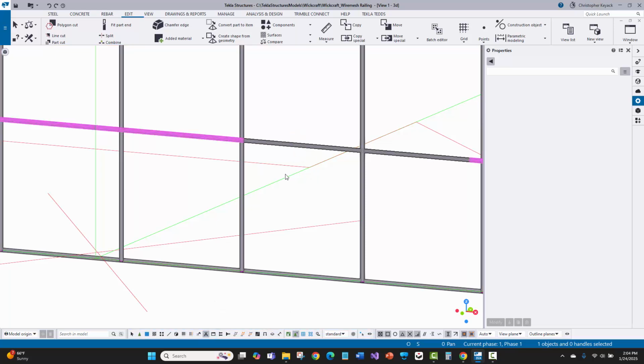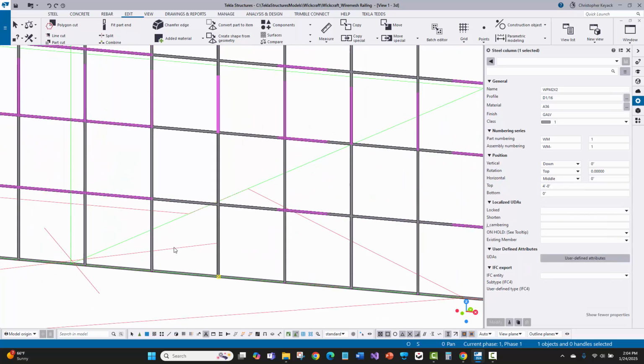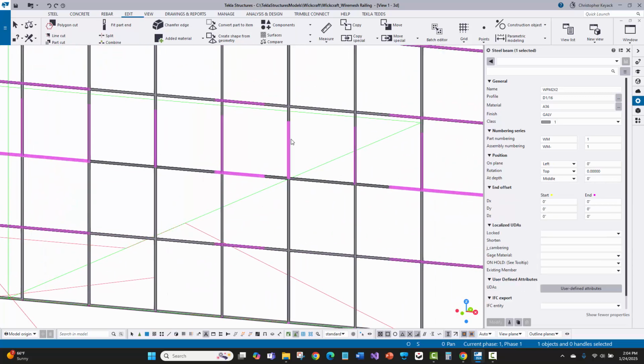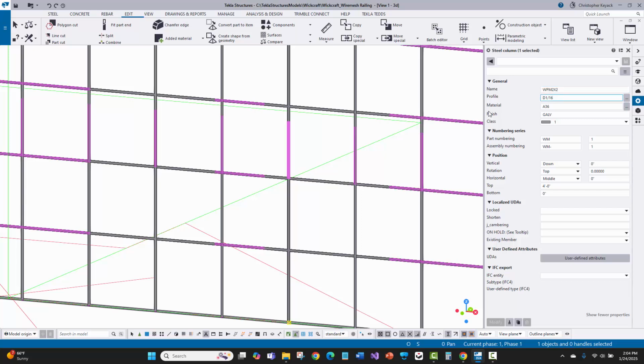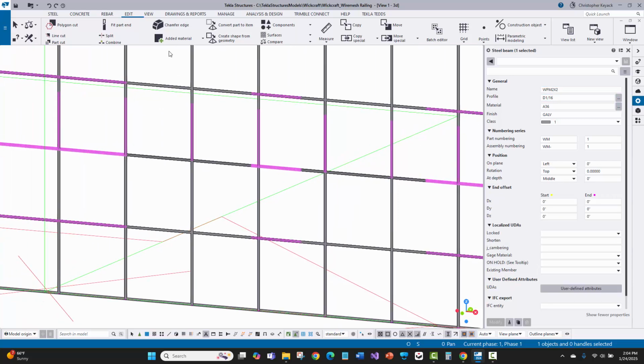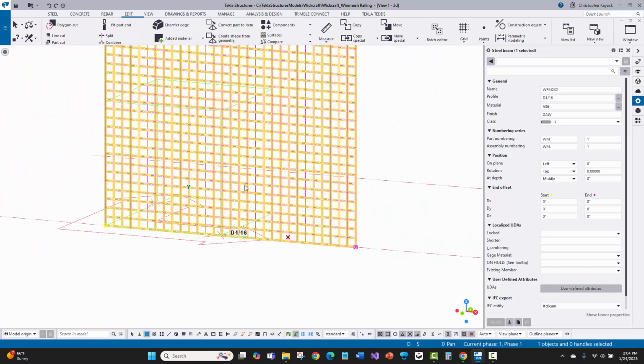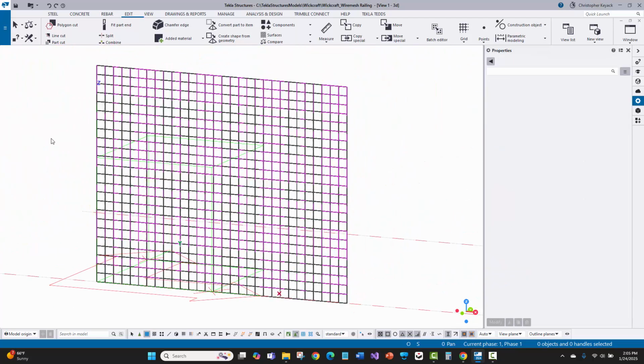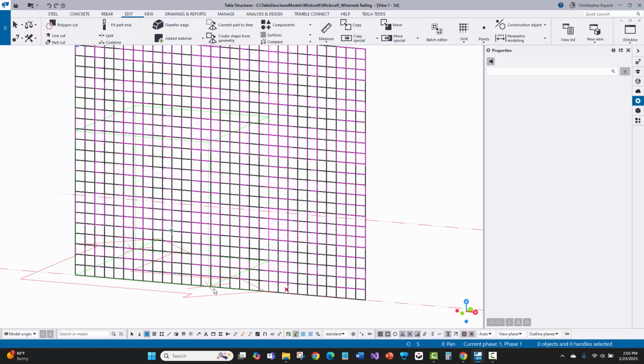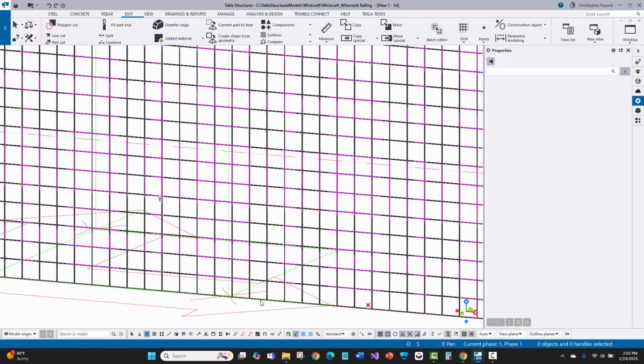So when you do that, now when I come back, look at this, I'm getting to the individual part adds that this did. And you can actually change and adjust those. And you can always come back in here and explode this so that it goes back into separate parts and you can modify it. But when I go back to selecting parts, you'll see that if I click on any of those, it highlights the whole object and all those part adds as one object. So this is step one, right? Is to just join these two things together as one unified solid or part.